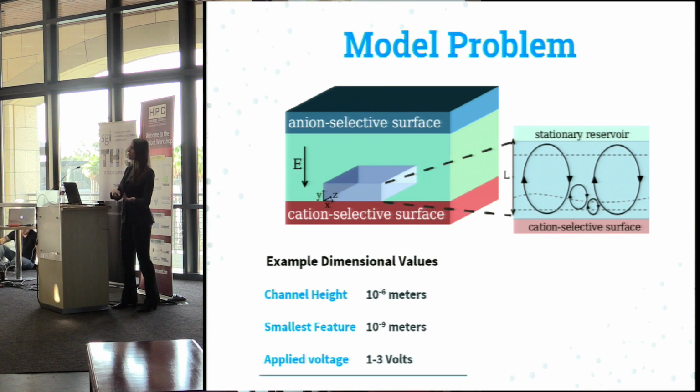When they think about computational fluid dynamics, they think about flow around an entire aircraft. But if you're doing a CFD simulation of flow around an aircraft, for example, like a Cessna, the entire length scale of that plane is on the order of tens of meters, and you probably need to resolve physics down 3 or 4 orders of magnitude to the scale of centimeters. So what matters is not the physical size of the problem, but the relative range of length scales that you have to resolve.